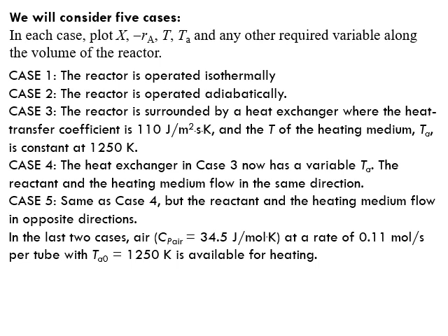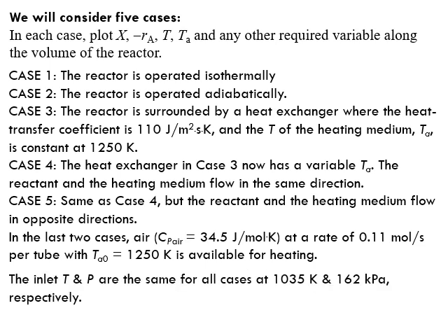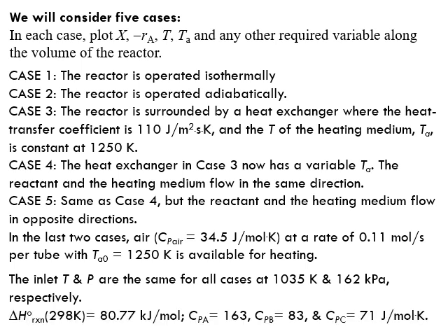In the last 2 cases, air with this given Cp at a rate of 0.11 mole per second per tube with Ta0 of 1250 K is available for heating. The inlet temperature and pressure are the same for all cases at 1035 Kelvin and 162 kilopascals respectively.